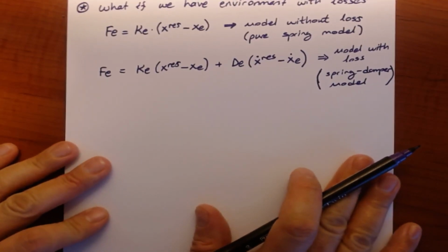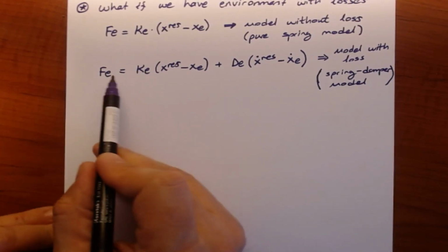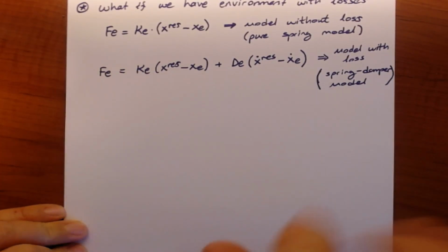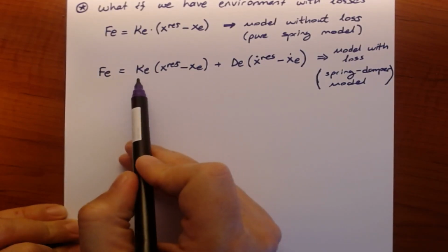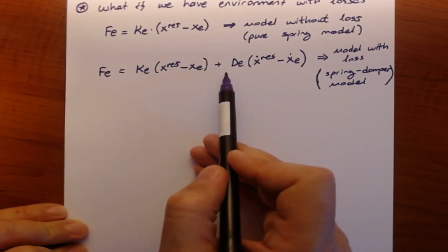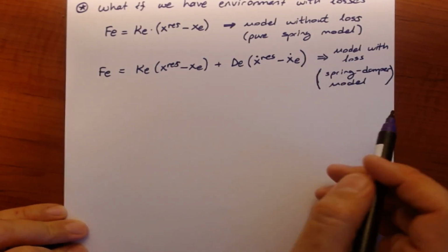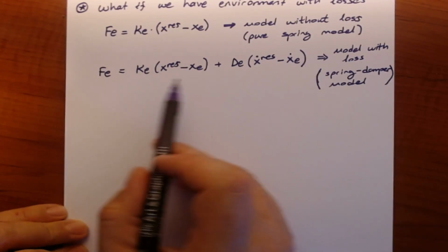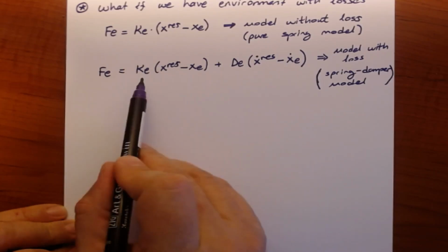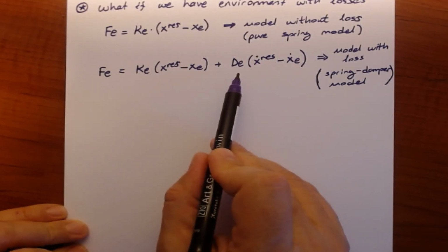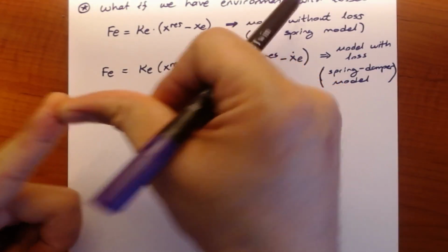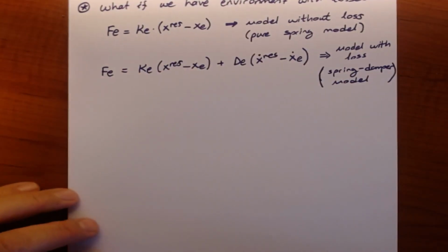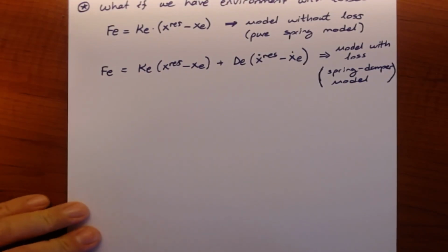But you know, for most of the applications, when you have an industrial plant, when you have standardized force control applications, it's not too difficult to come up with the KE and DE parameters of the substance to be processed under the robotic system. So once you make this analysis, once you know the stiffness and the damping of the environment where you are interacting with your robot, then it's not too difficult to carry out that motion control algorithm.